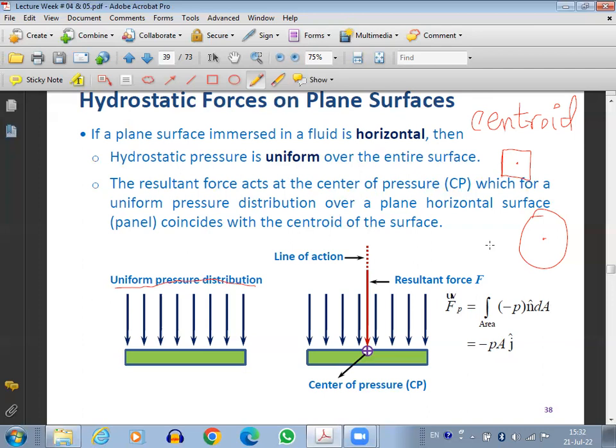Geometrically, it is a sphere, irrespective of how the mass is distributed. So the centroid would still be in the center of the balloon, but the center of gravity would not be there because the mass is unequally distributed. The center of gravity normally shifts towards where you have more mass. If more mass is on the upside, the center of gravity will shift up.